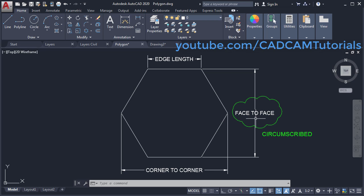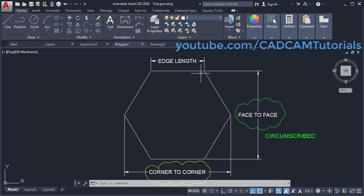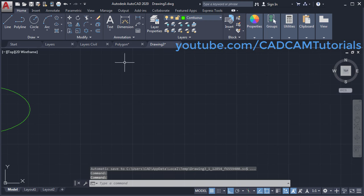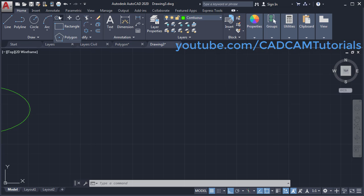If the dimension given is face to face, then you will have to use the circumscribed method. And if the dimension given is corner to corner, then you will have to use the inscribed method. And for the edge length, the edge method needs to be used. So in this way you can decide which method to be used based on the dimensions. I will create one polygon. Click on polygon. When you use some command, it comes on the top automatically. If we click on this arrow, we can see that polygon is the second command and rectangle is the first command. But we have clicked there previously, therefore it came on the top automatically.